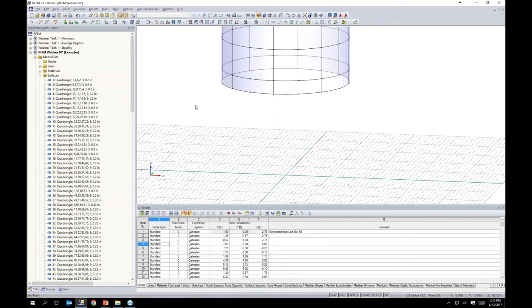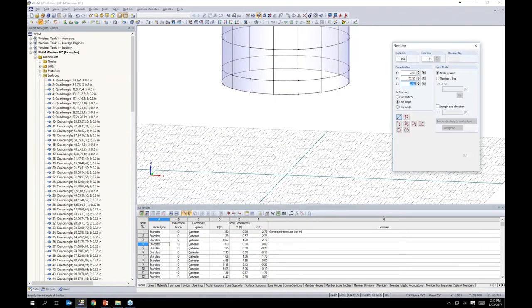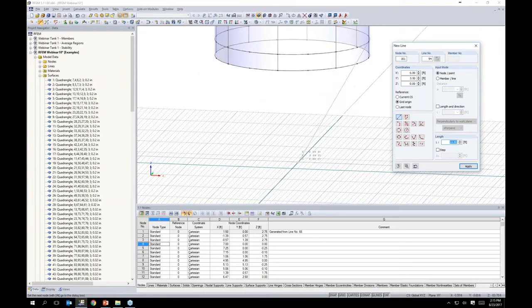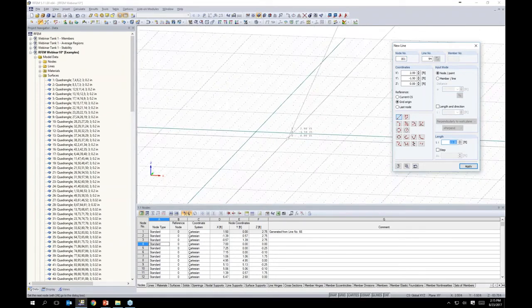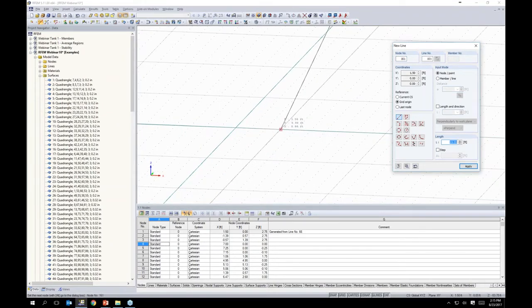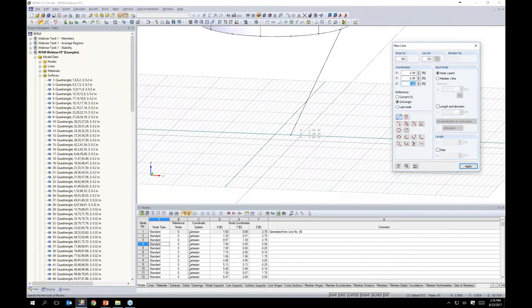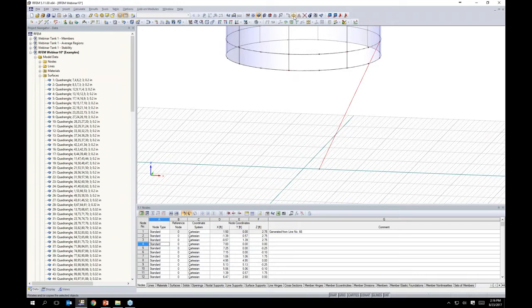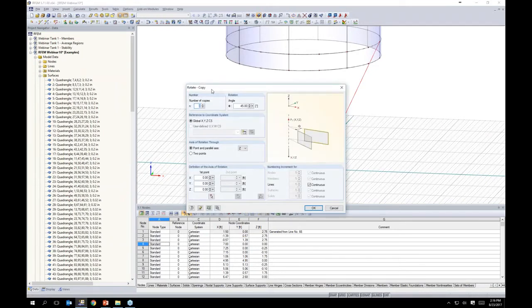So moving forward with the hopper, I'm going to select a straight line element that we have seen previously, and I'm going to snap to a point on my cylinder and zoom in down here onto my drawing grid to a point 1.500. Now, just like what we saw before, I'm going to highlight this line element. I'm going to use the rotate tool, 8 copies, 45 degrees, about the origin. That's great.